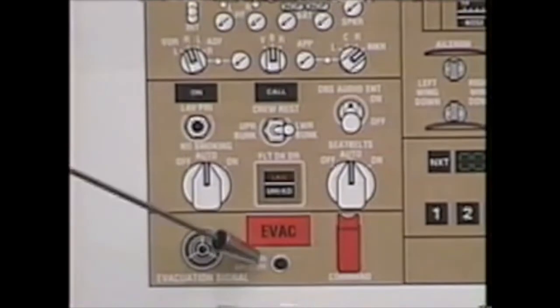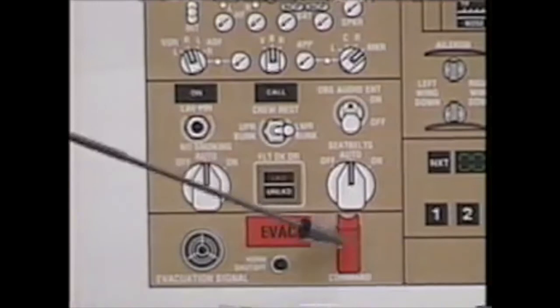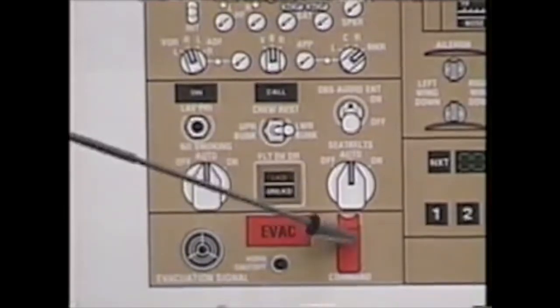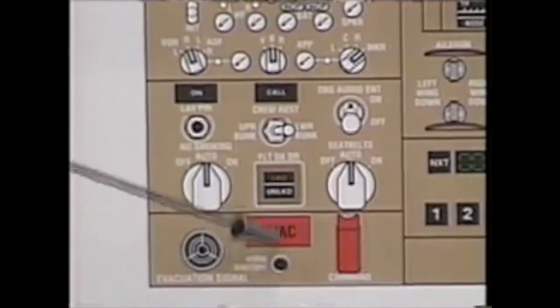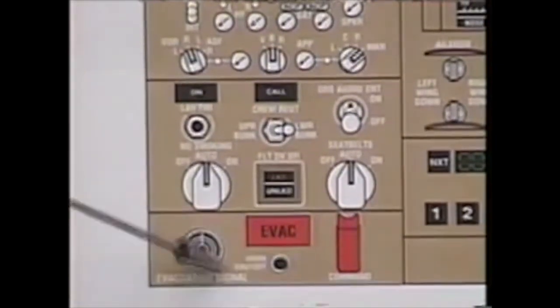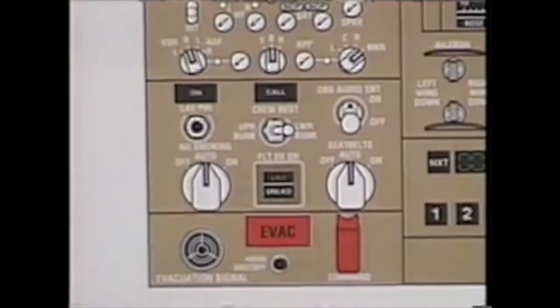Evacuation control panel, left aft end of the center aisle stand. Immediate action for evacuation is ATC notify, call for the QRC. There are numerous switches throughout the airplane, flight attendants' positions at the doors, upper deck as well. Any one switch anywhere on the airplane will activate every light and every horn on every panel. Pressing the button on that panel will silence the horn on that panel only. The light continues to flash until all control switches are returned to normal.